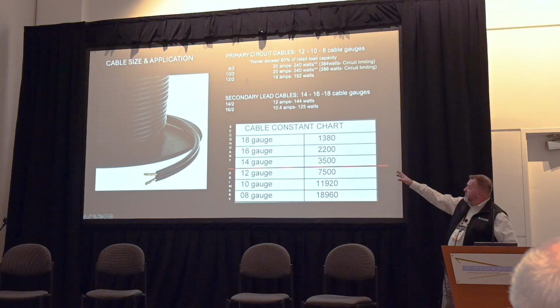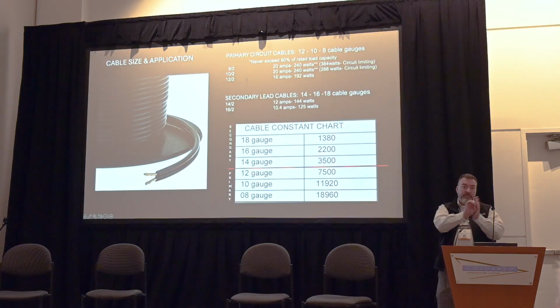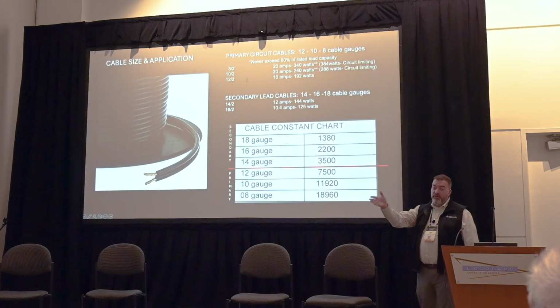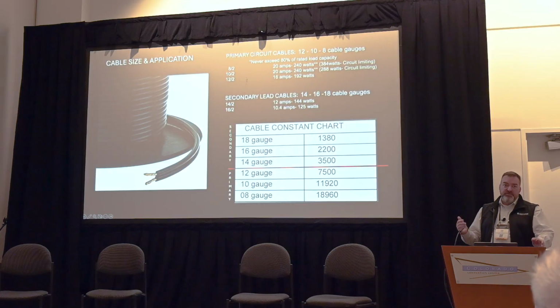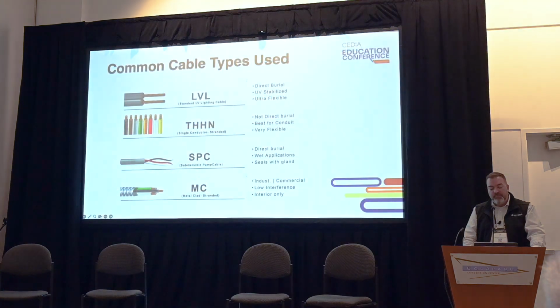So never use a 14, 16, or 18. Those are secondary cables that you'll see from a fixture lead, short, coming back to a hub connection or back to the primary circuit. You'd want to use a heavier circuit to make sure you're carrying that load out. Most common is 12 gauge with LEDs. You have a voltage range usually between 12 to 15 volts on most of those. You want to keep them as close to 12 to 13 as you can, but they have a pretty wide range, so they're pretty forgiving. But rule of thumb, don't ever use a 14 to run your home run circuits on a 20, 25 amp circuit. You're just asking for trouble.